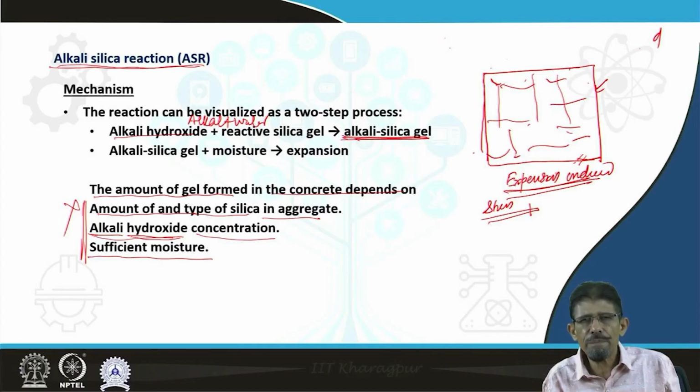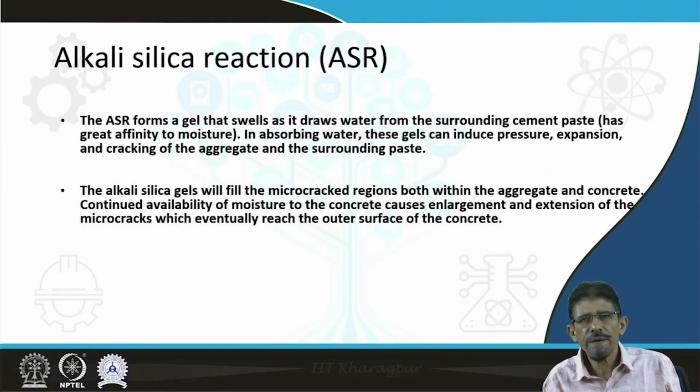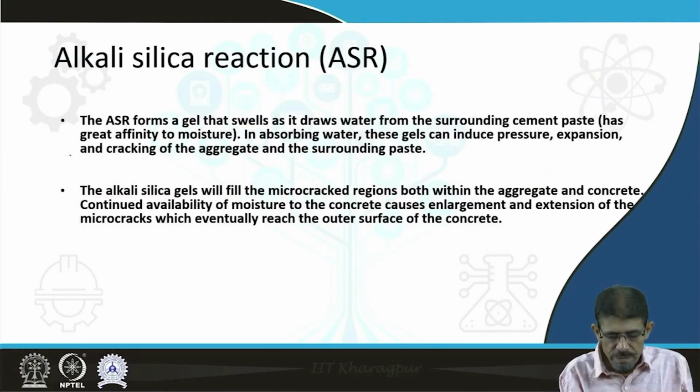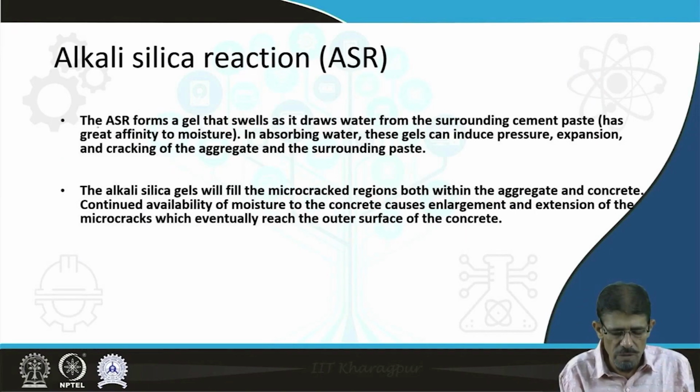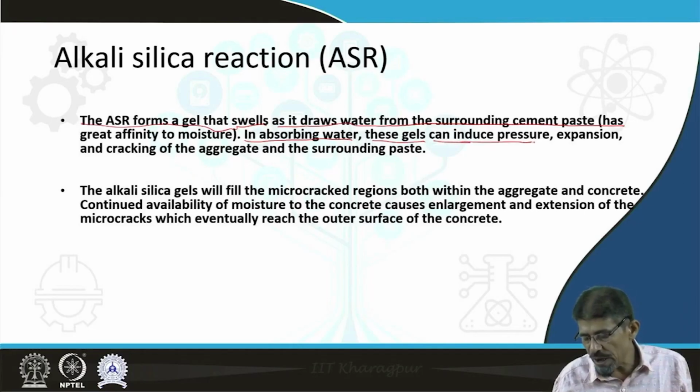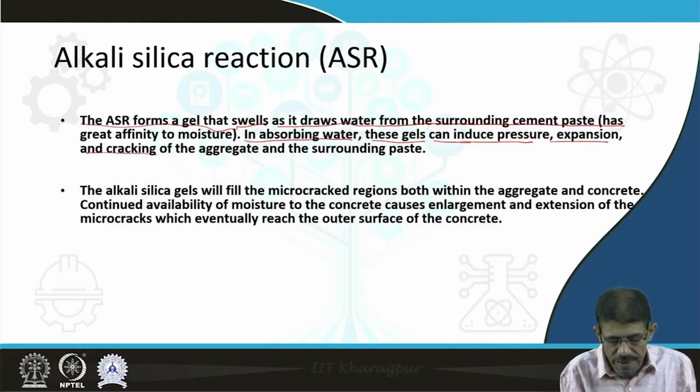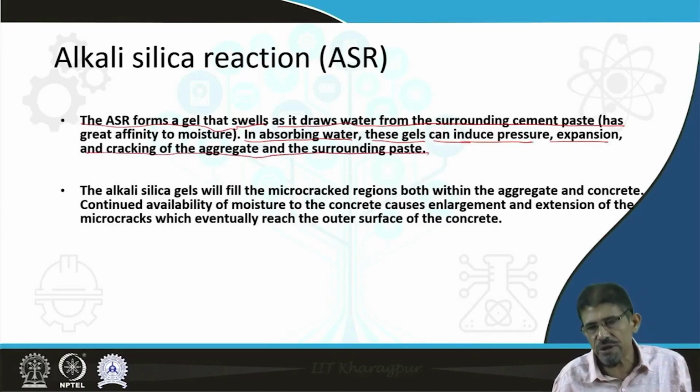Next type we are having; first we are going to complete ASR, then we will discuss carbonate. The ASR forms a gel that swells as it draws water from the surrounding cement paste. In absorbing water, the gels can induce pressure, expansion and cracking of the aggregate as well as the surrounding paste, resulting in fracture, cracking or deterioration of the strength of concrete.